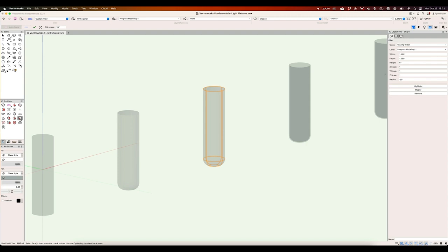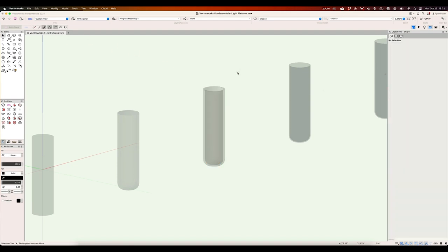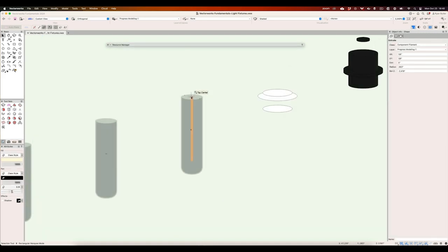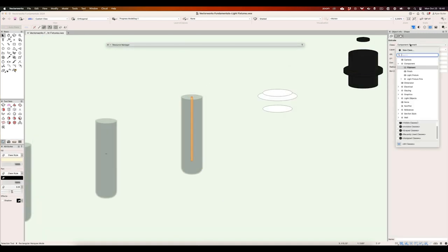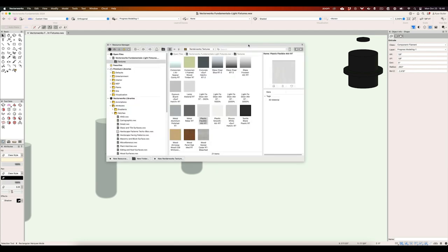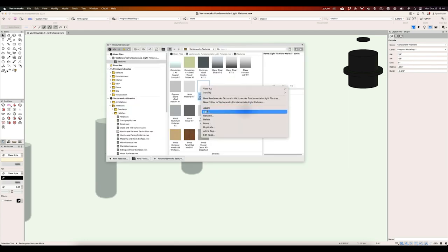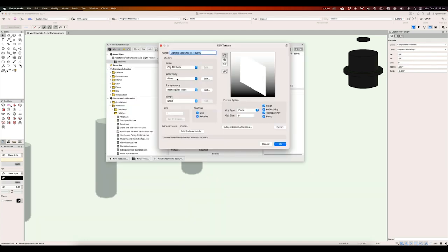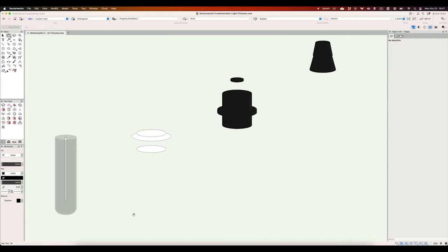To make this shape hollow, the shell solid tool is the way to do it. Select the tool and set the desired thickness, then select the face of the shape you want to have an open edge. To model the filament, it's another extruded circle, but this time the extrusion has its own filament class. In that class, a glow texture is used. More on that later.